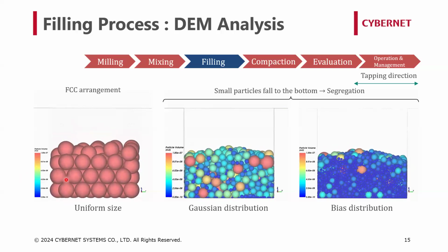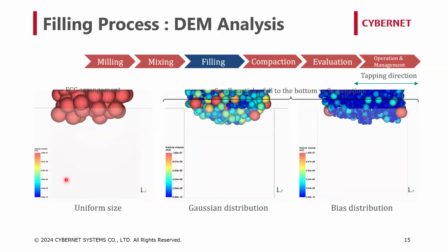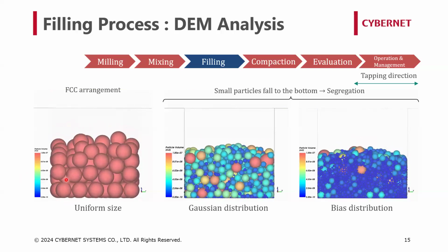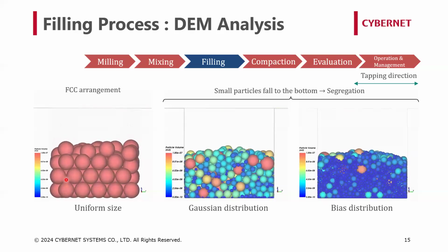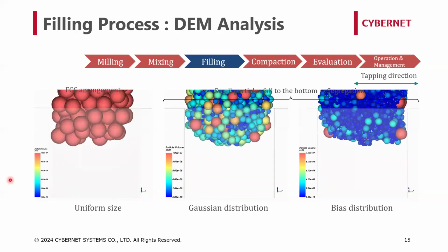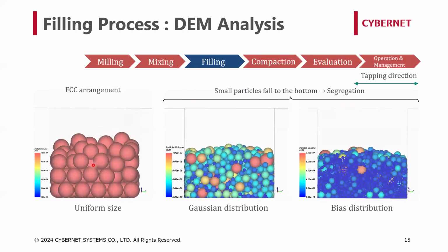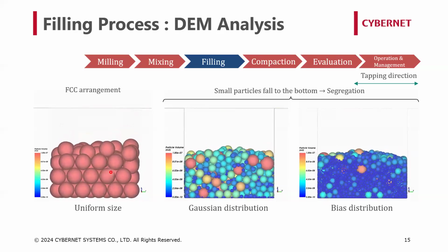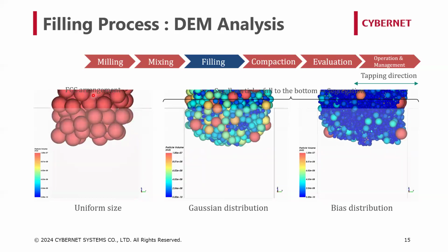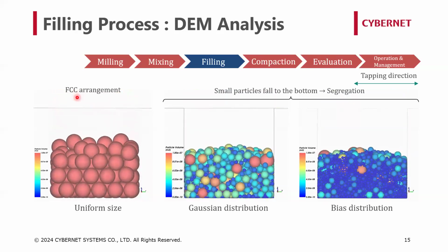The particles are randomly arranged immediately after they reach the bottom, but by applying vibration, the particles become regularly aligned in phase in the height direction, and the particles of the second phase are stably arranged in the concave region created between the particles of the first phase, eventually converging to an FCC crystal structure.